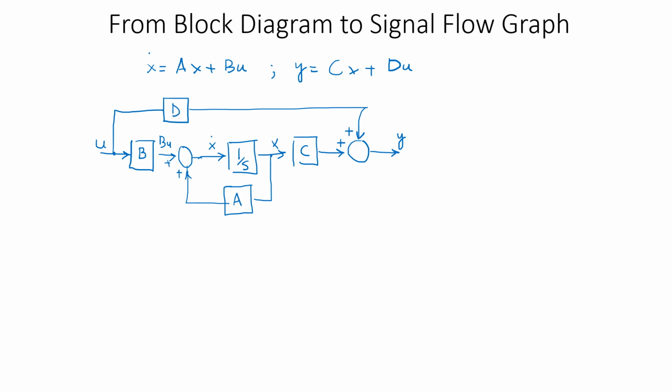Now once you have got this block diagram available with you, you need to transform it into a signal flow graph so that I can make use of Mason's loop rule or Mason's gain formula to further analyze what is happening inside the system. We will see that later on, but at this particular stage I need to convert this graphical block diagram into another graphical form of representation called SFG or signal flow graph. So let's try to do that.